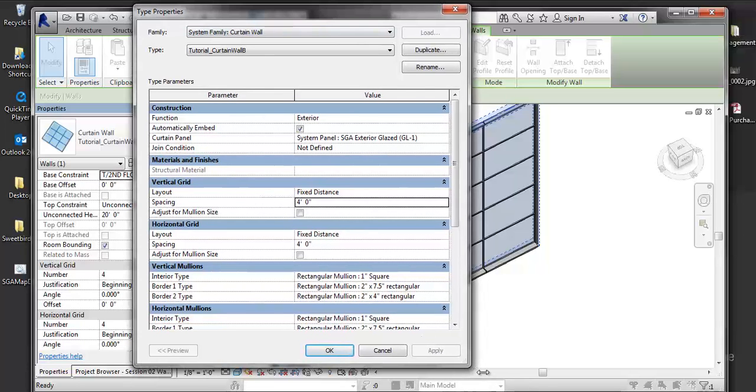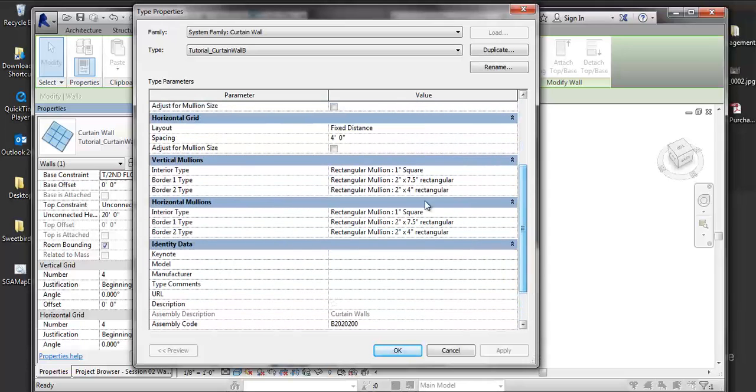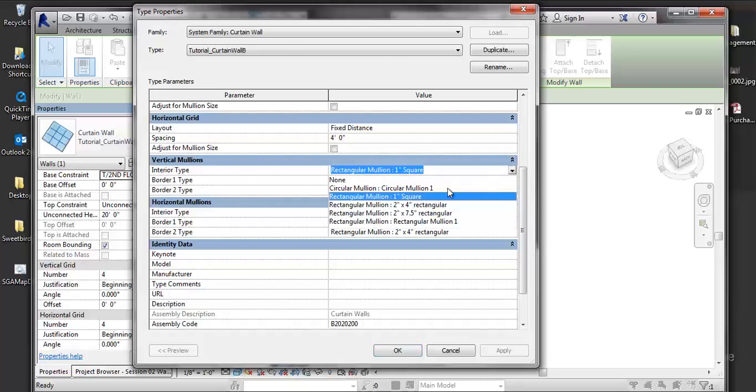Other things you can do with it are loading in the mullions. So down at the bottom, each one of these, and this is kind of going down where there's always a hierarchy of situations, and we haven't got into modeling yet, so understanding the kind of sweep that's happening. So everybody's made a sweep in Rhino or CAD, right? Yeah, so the same thing is there. So you consider the grid line that you're dividing out to be the rail curve, and then your profile is that sweeping element, right? So we're loading in families that house that profile and allowing that sweep to happen.